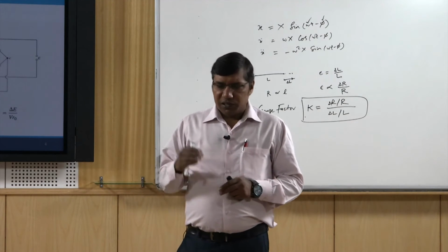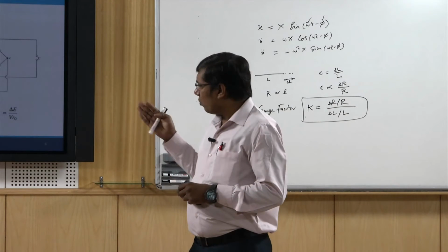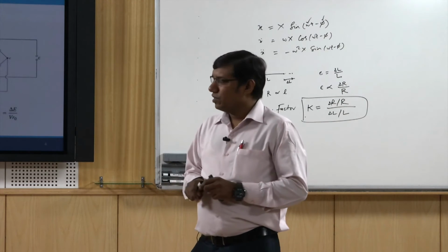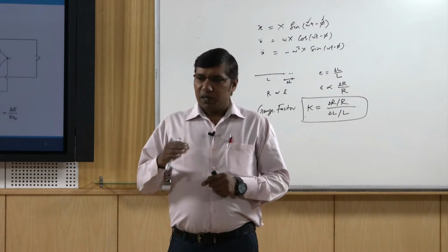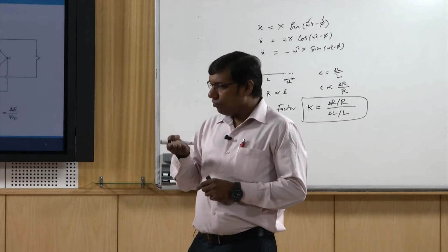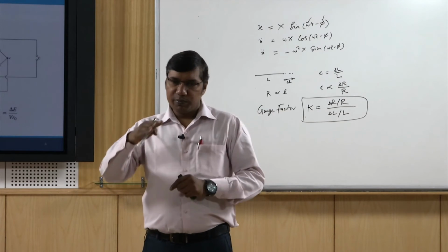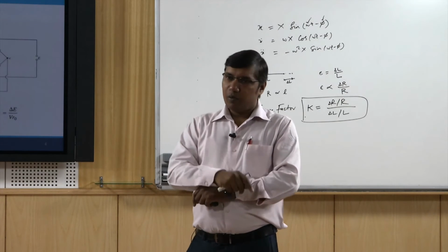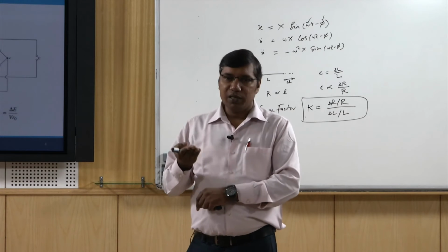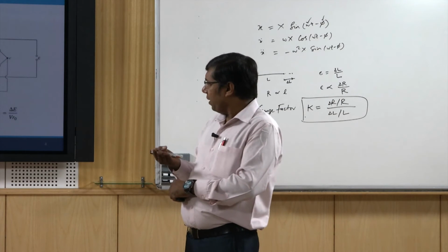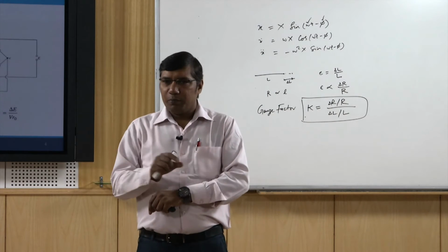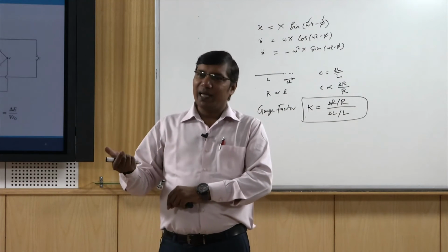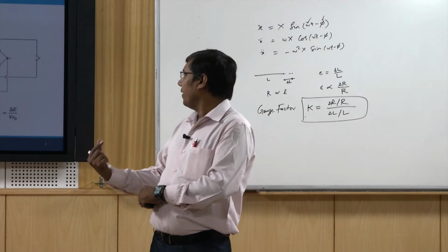The strain at the location of the strain gauge will depend on the displacement x, because the more it is displaced from its equilibrium position, the more strain there will be. So, by measuring the strain and relating the strain to x, we can measure x.